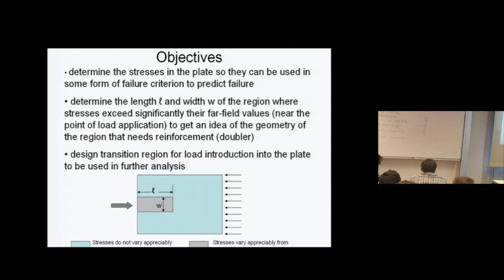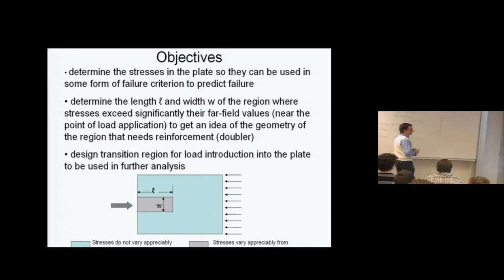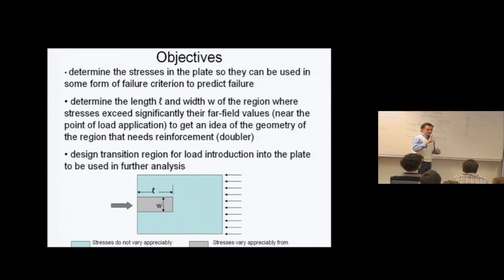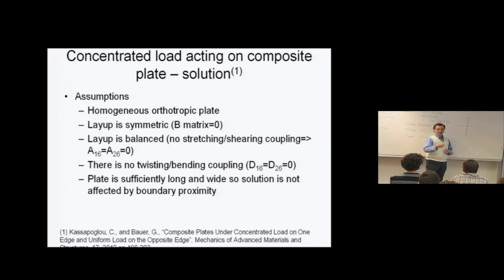These assumptions reminded me of one thing I wanted to say. I keep mentioning quasi-isotropic, and just for purposes of definition, it's also in the text in the book. One way to create quasi-isotropic laminates, or the best way, is to make sure that you have exactly the same number of fibers in every direction.